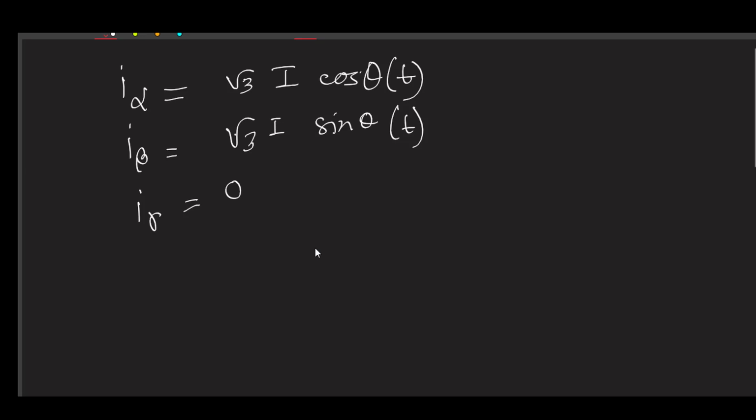We can consider this I gamma responsible for our zero sequence component. Even if it is unbalanced but symmetrical, all the time we will get I gamma equal to 0. We can visualize I gamma as perpendicular to the plane, and therefore it is orthogonal, and the transformation matrix is always invertible.